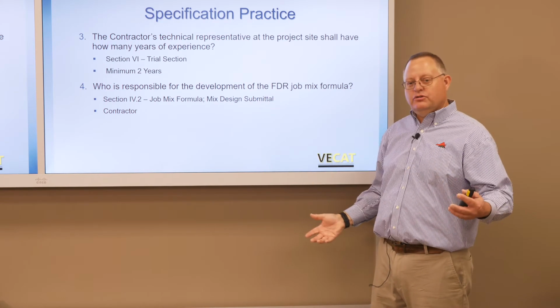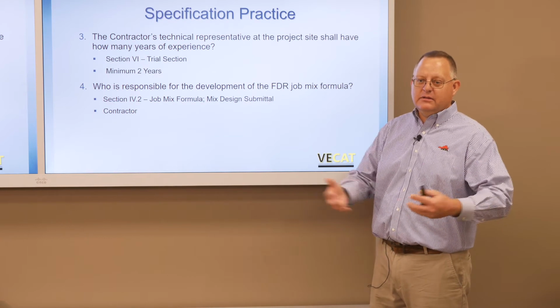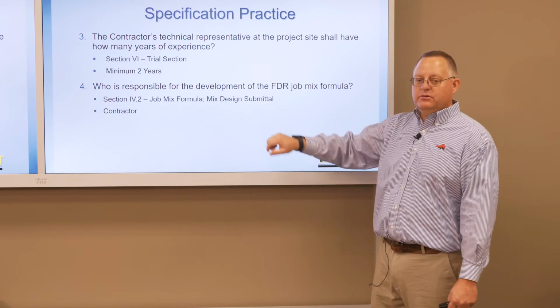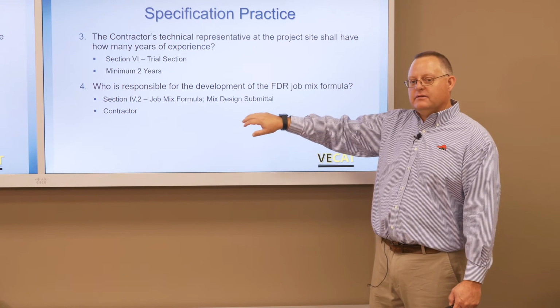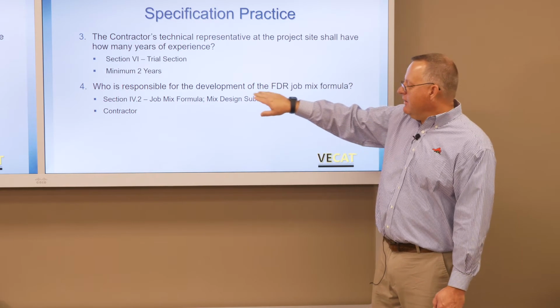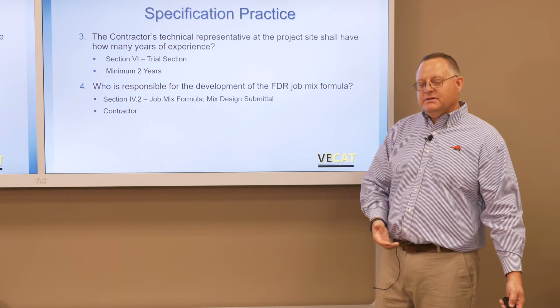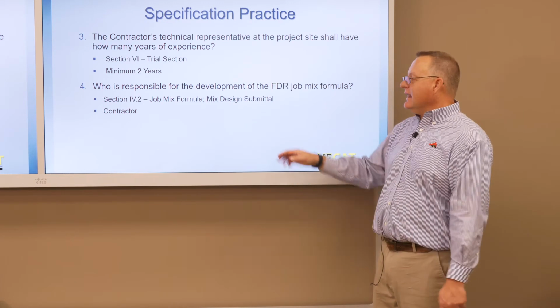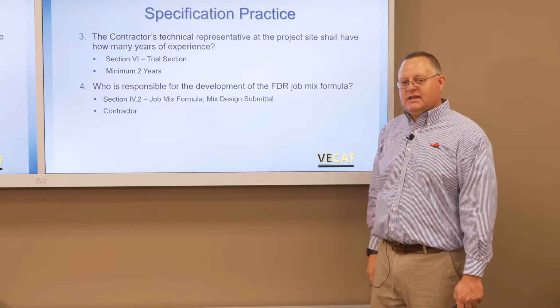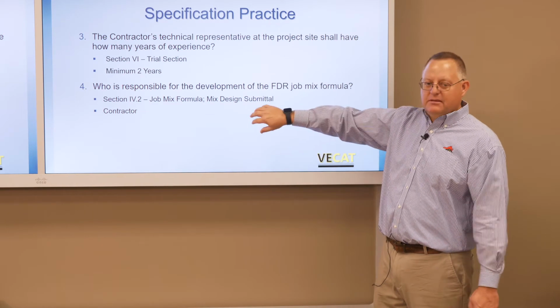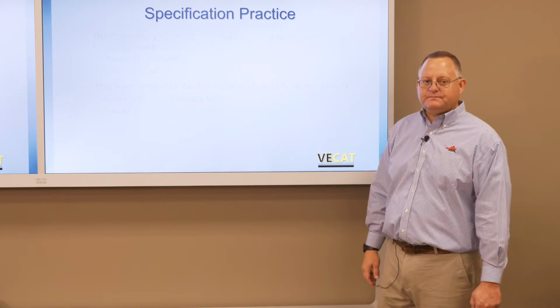So you may have a unique project where the contract tells you what to do. You follow that because it overrides. But in most FDR projects, the contractor is responsible for obtaining the material, taking it back to the lab, making the mix designs that exceed the minimum set up in the contract.